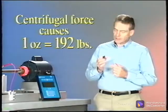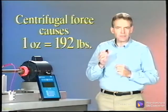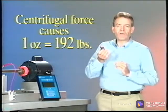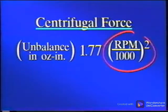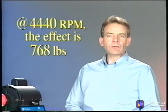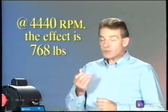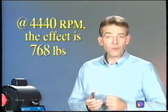Due to centrifugal force, this 1 ounce of unbalance has an effective weight of 192 pounds, which means that this 1 ounce puts an additional load on the rotor of 192 pounds. The equation that describes this has a squared effect with respect to speed. This means that if the speed is doubled, the effect of the unbalance is increased by a factor of 4. In our example, doubling the speed to 4,440 RPM would increase the effect of this 1 ounce of unbalance from 192 pounds to nearly 800 pounds.